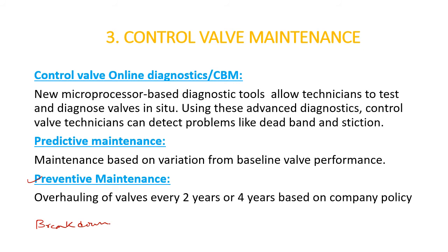And there is another, that is CBM, or condition based monitoring. In condition based monitoring, positioners now come with diagnostic tools where you can monitor the performance of the valve online, and if something goes wrong you can take action accordingly. There is various software, like Fisher has ValveLink and Metso has Valve Manager, and this software can be installed in the instrument asset management system like Yokogawa PRM.